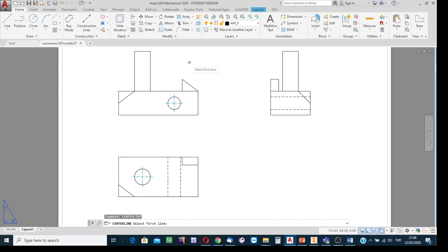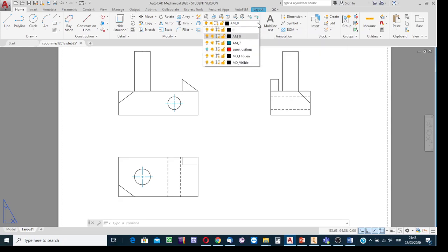But sorry, before indicating the limiting lines of the projection of the revolved feature, let me press the escape button and cancel this symmetry axis invoking process because I forgot to select the axis layer. To be able to have the longitudinal axis created in the same layer, from this list select the AM7 option.